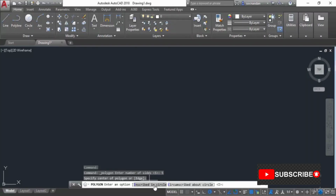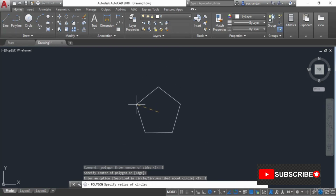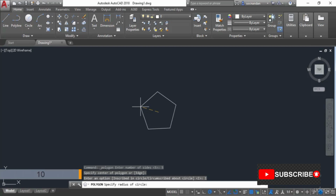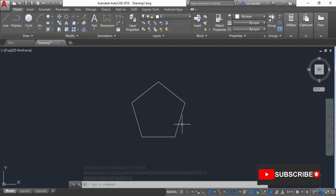So in the first case, I'll select inscribed in a circle. And now here we have it. In this case, you can simply see that my cursor is on one of the vertices of this polygon, and the imaginary circle is passing through all of these 5 vertices of this polygon. So now we need to enter the radius of the circle within which this polygon is inscribed. So I'll enter 10 as the radius and press enter. So here we have this polygon. Now the circle which is passing through all of these vertices is the circle with a radius of 10 units.